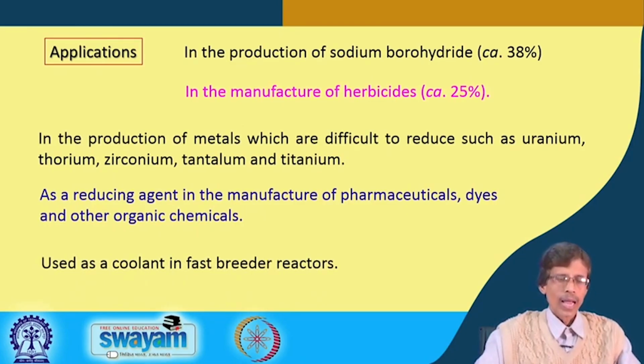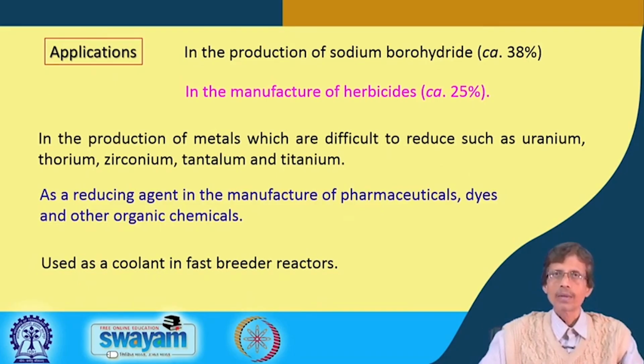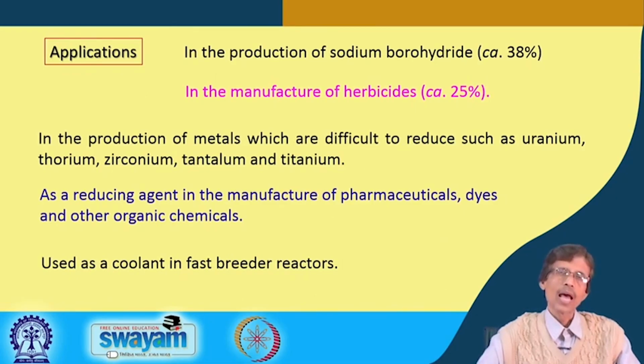And it is also very useful as a coolant in another area, the nuclear reactor. In nuclear reactors, we know one type is the fast breeder reactor, and in those fast breeder reactors we use molten or liquid sodium. The molten sodium can be useful as a coolant, not water, not any other heavy organic liquid, because they have a huge evaporation effect, like glycerol or any other. So the metallic sodium, that means the liquid or molten sodium, can be useful as the coolant.